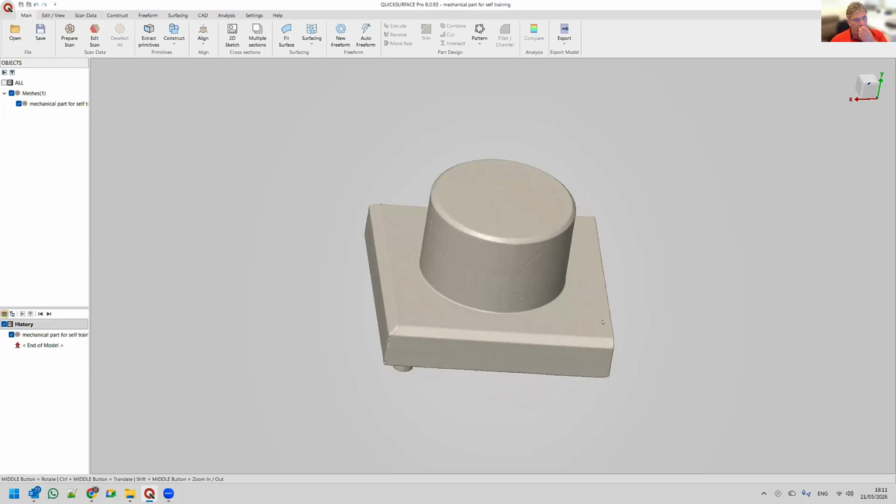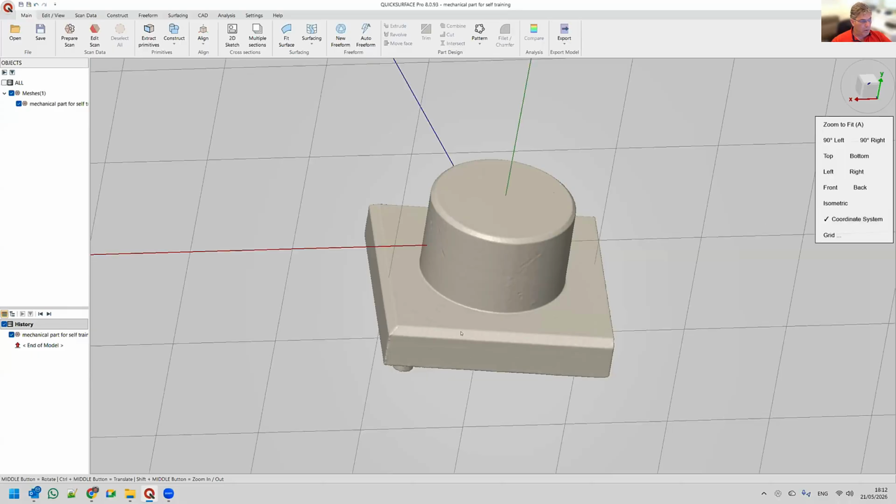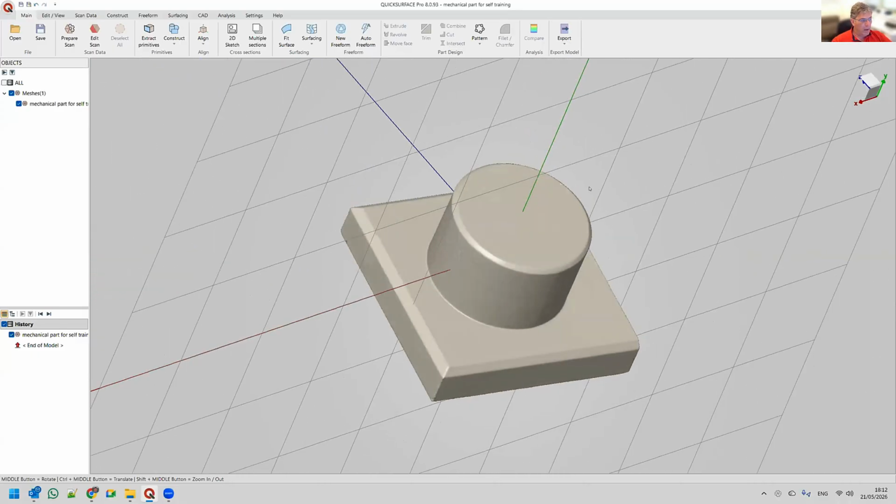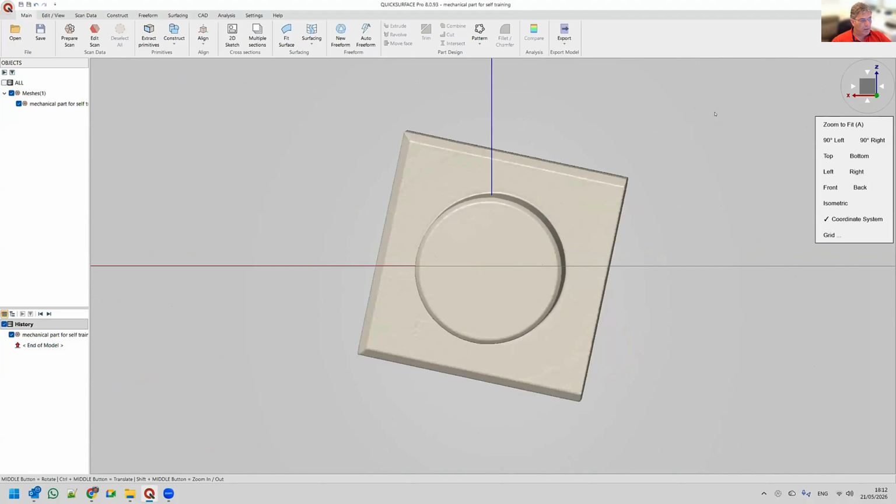It always starts with the simple part. So the first very important thing that we see with the 3D scanning is what we call alignment. Alignment is mathematically positioning the object into a correct coordinate system. A coordinate system is something that you can see on the screen that defines X, Y, Z. This would mean that if I place this in the standard views, the object should be nicely placed, and not only nicely, but accurate. If you're talking about manufacturing, then everything needs to be perfect.